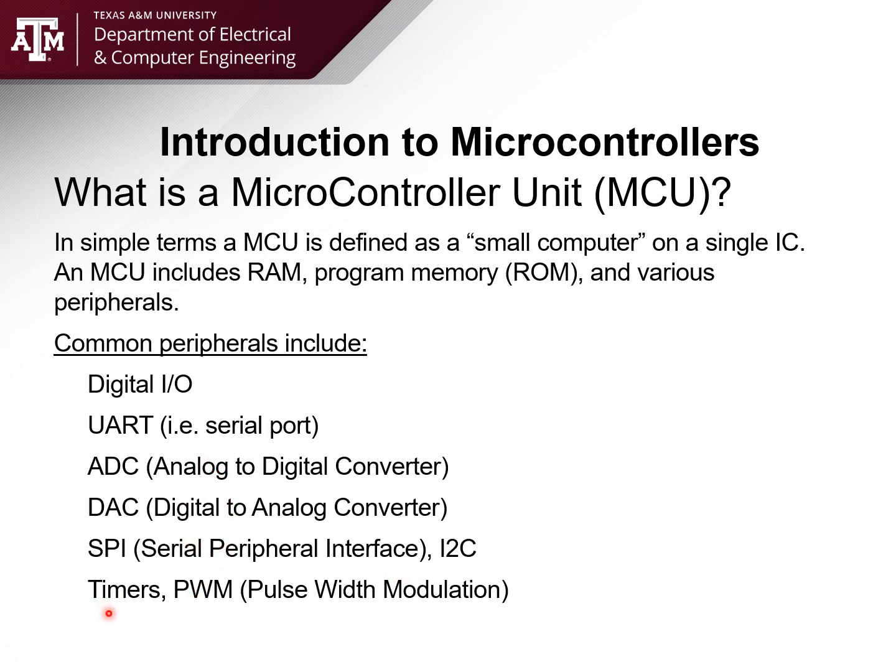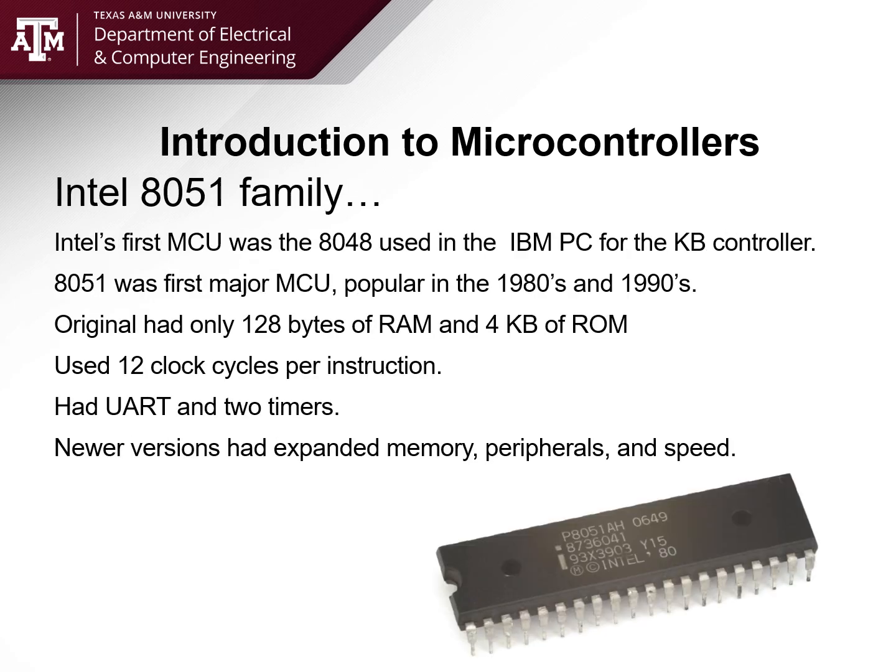And then we also have timers and pulse width modulation. If you remember from the lecture the other day on transistors, where I introduced pulse width modulation, most peripherals inside a microcontroller unit can support pulse width modulation. So you can do motor control where you're using pulse width modulation as a method for doing that control, or heaters, etc., as we were talking about in that part of the lecture. So these are very common peripherals in pretty much every microcontroller that you can purchase today.